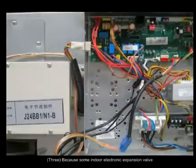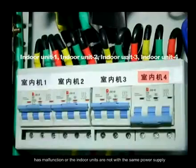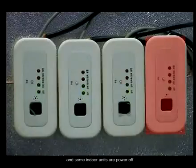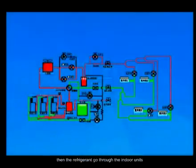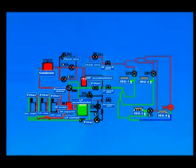3. Some indoor electronic expansion valves have malfunctions, or the indoor units are not on the same power supply and some indoor units are powered off. Then the refrigerant goes through the indoor units which are powered off or the electronic expansion valve that is stuck. It affects the system running performance.